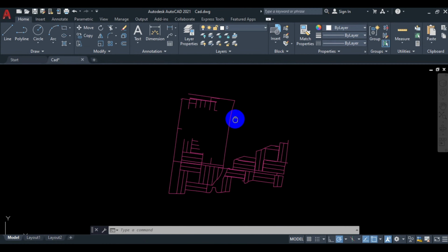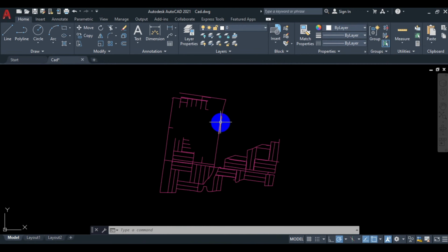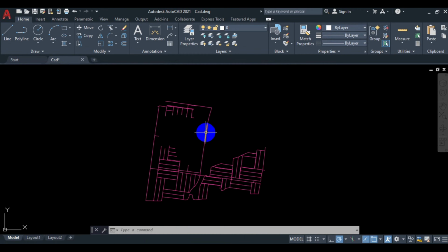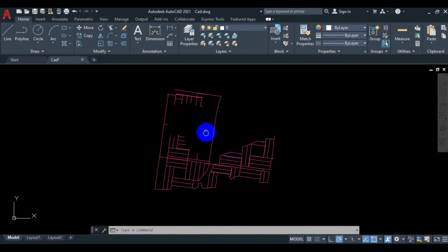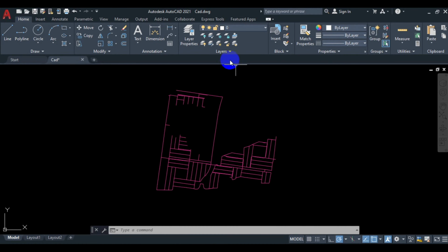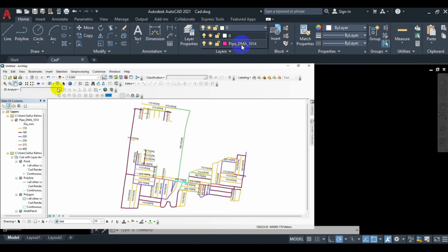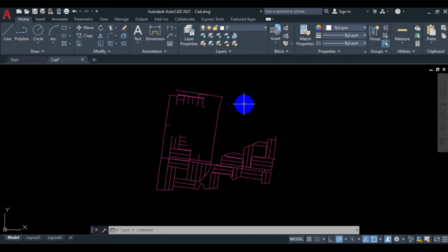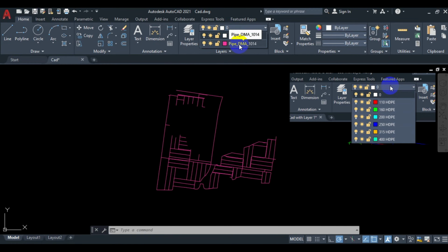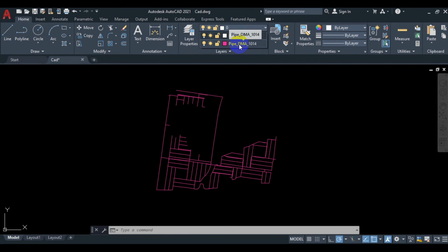Here we want to see the field of pipeline diameters that have been converted into AutoCAD format, but the problem is the field of the shapefile is not included in a layer of the AutoCAD. So click on here and you can see that only the name of the shapefile has been added in a layer of AutoCAD. Now I will show you the simple tricks for getting the field of the attribute table into the AutoCAD layer when converting data from the shapefile feature classes. I will show only one method, though we can do it in various ways in ArcMap.